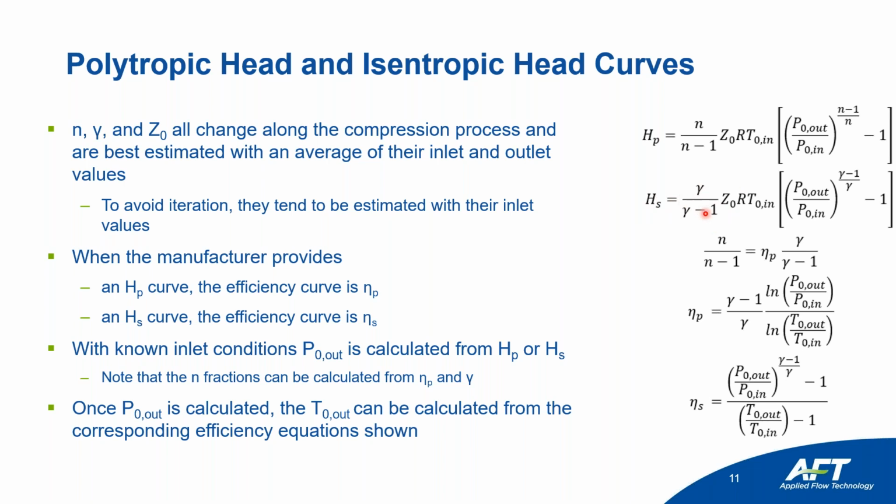That's a bit easier, you'll see, for the isentropic head, and that's because the isentropic head is using the isentropic expansion coefficient term, which, as I mentioned, isn't quite specific heats for real gases. But anyways, it uses that isentropic expansion coefficient term, which is easier to have available than the polytropic.